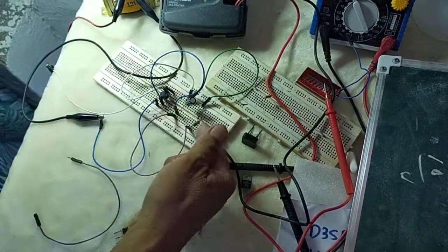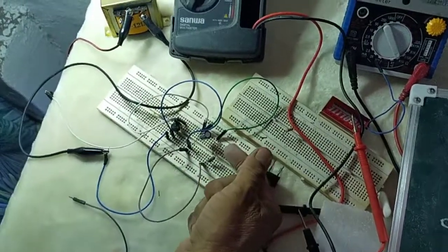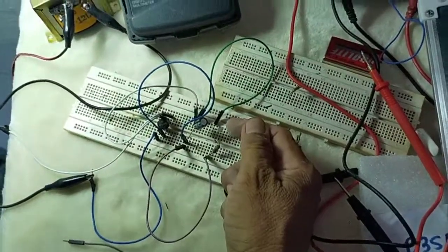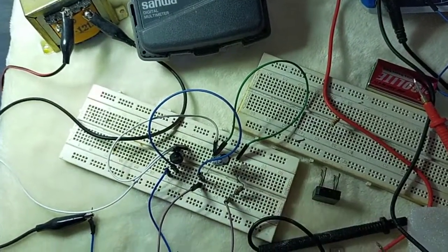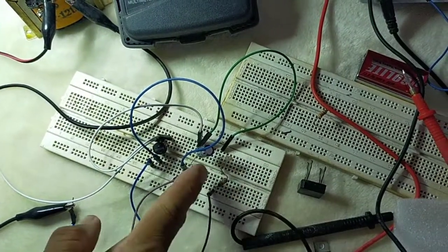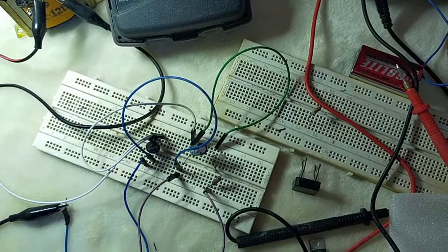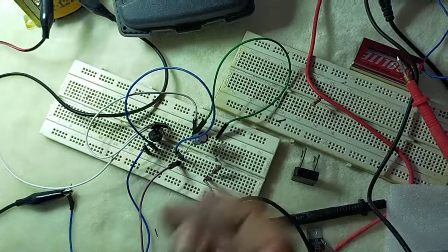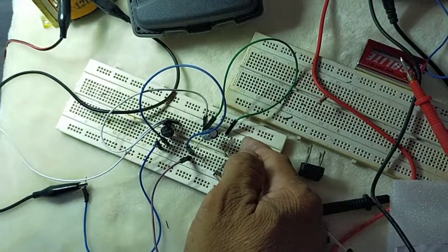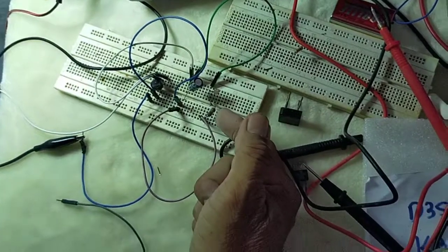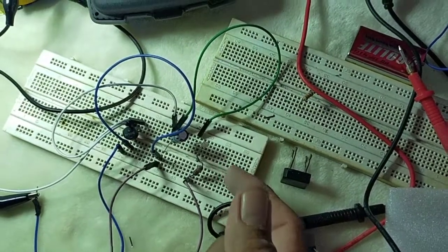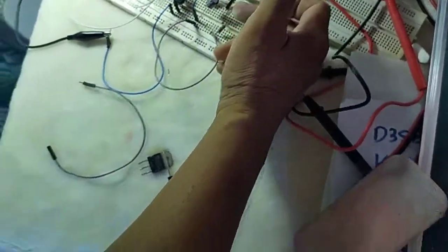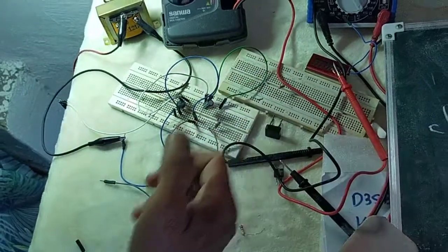So without a resistor, usually the light emitting diode will blow, would be damaged, because the required amount of voltage for this diode is only up to 3.7. But the voltage now applied to this diode is already 16 volts. So the diode could no longer control the intensity of the voltage. So it damages. That's the importance of connecting a resistor in series, in order that it limits the current or drops the voltage. Only 3 point something volts should be across this light emitting diode.